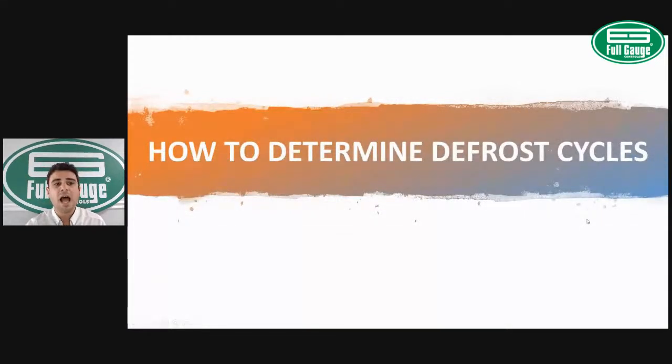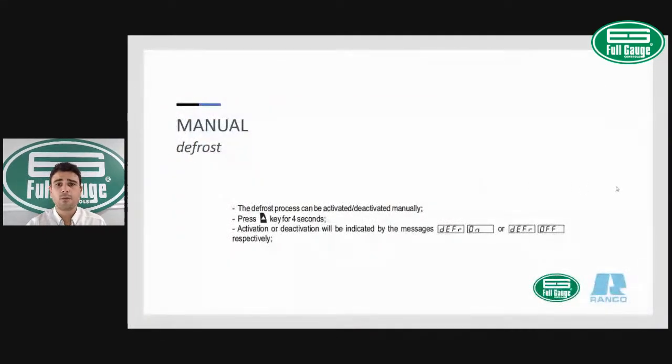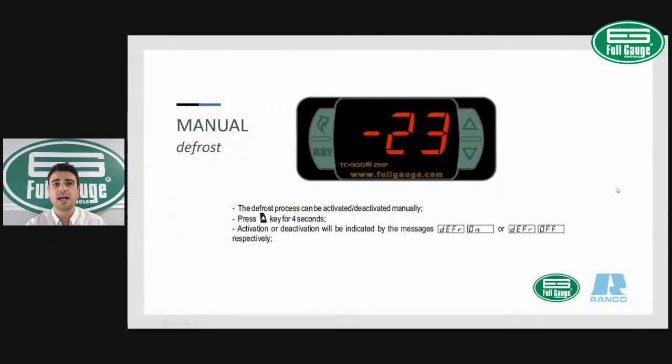How to determine defrost cycles? So the first defrost cycle we're going to take a look at is the manual defrost. Manual defrost is a forced defrost. When you adopt digital controllers, most of them will provide you the option of forcing a manual defrost.